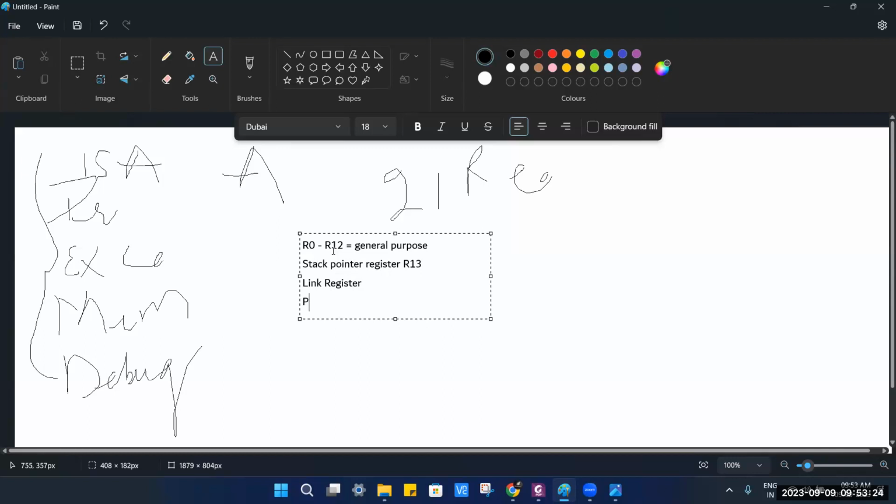And the program counter, you are also aware, keeps track of the current instruction being executed; where the current execution is, it points there. Then there is the PSR, the program status register. Operation results, conditional flags, and so on are contained in that register. You can prepare this as a constant, static, volatile pointer and then use a variable to read from it. Everything from the conditional code flags to the interrupt control bits is in the program status register.